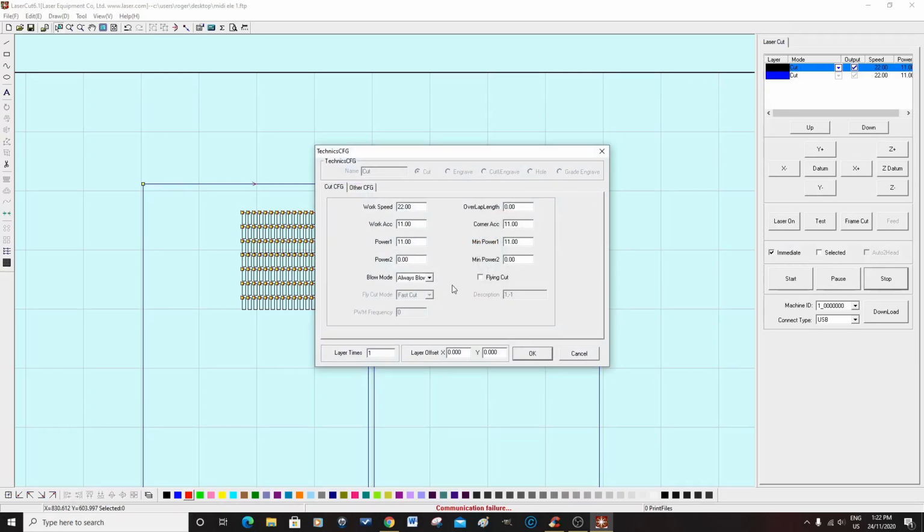Okay, so now we come to set the laser speed and feeds and power. I know through experience, and you can actually find this out through trial and error: don't go straight in when you get your laser and think that you know, or even attempt to do a complex job. You need to start right off at the very beginning and just start cutting little squares. Every material requires a different setting of speed and feeds.